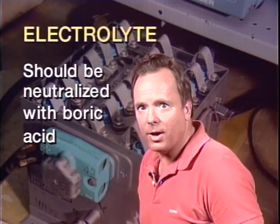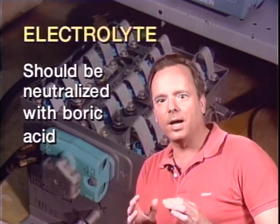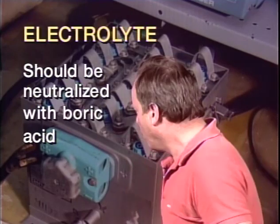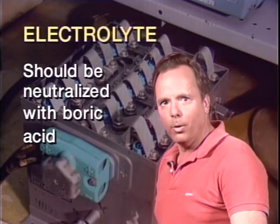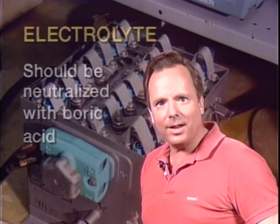All right, nickel-cadmium battery cases and drain surfaces which have been affected by electrolyte should be neutralized. What should you neutralize them with? The answer is a solution of boric acid. And that is everything they ask you about AC current and batteries on the written exam.